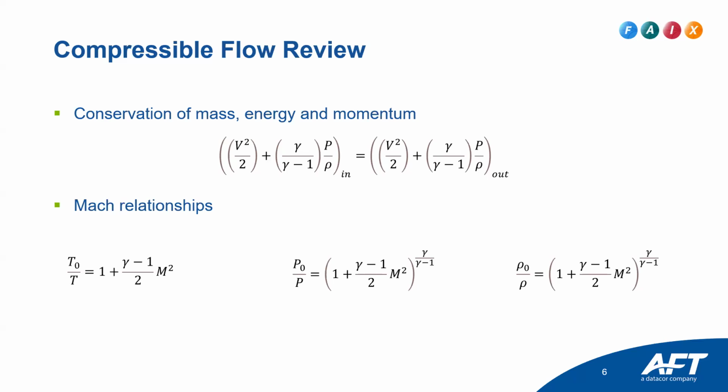My end goal is sizing orifices, but is there by any chance a webinar out there specifically for sizing orifices in Aero? Yes, I believe there is. The general approach is you would set up a system with a control valve there for whatever flow or whatever pressure you're trying to achieve. Then you can see the equivalent CdA that you would need for the orifice and size the orifice that way. Of course, you could also do it with the GSC module if you're wanting to do something that you couldn't capture using a control valve.